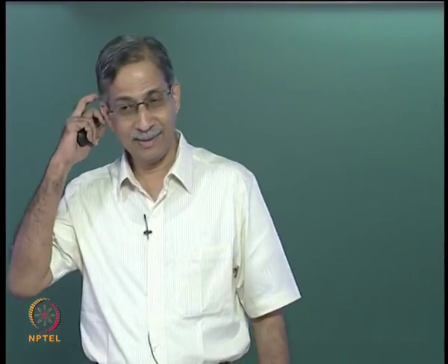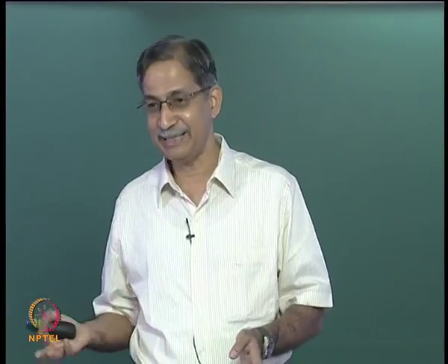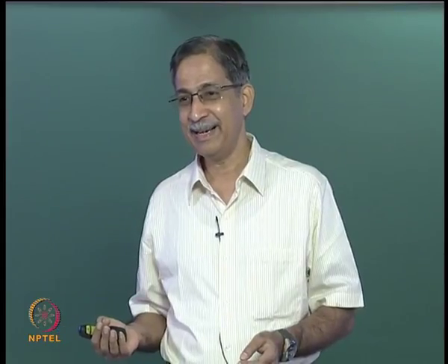Sorry? In element 2, there are no... We do not take advantage of it here. We do not take advantage of that hinge here, because that we will do when we ignore axial degrees of freedom. You understand? Here we are not taking advantage of the release there. You can do it. I am not taking advantage in this case, but I will take your suggestion in the next case where we ignore axial deformation. So your point is valid.